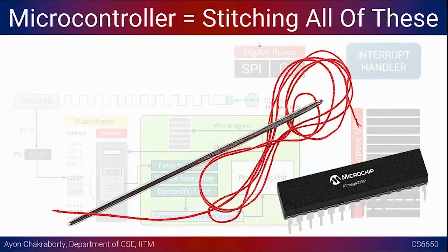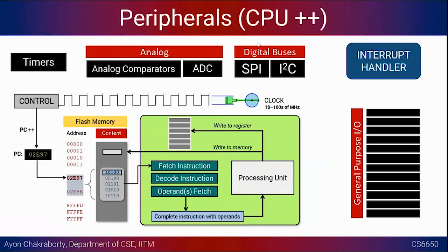So all the interfacing circuitry that we have seen around the CPU, the green part, as well as the clock. This is the core microprocessor, particularly the green part. In most microprocessors, you need to also supply the clock signal, whereas in a microcontroller there will be an internal clock also. And all these peripherals, the flash memory, everything, are not there. There's nothing there. So just the CPU.